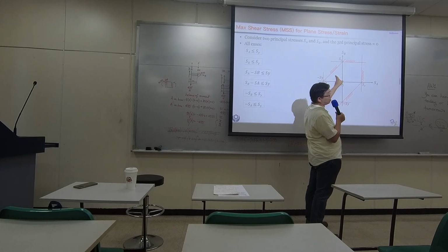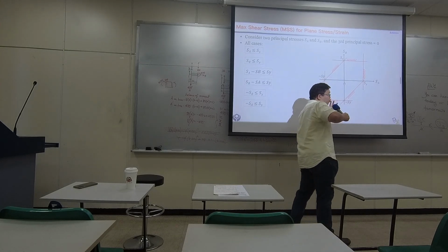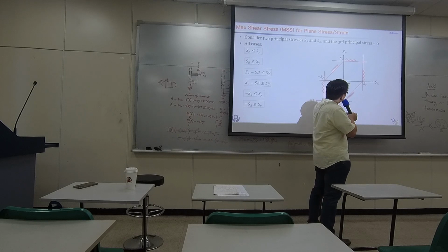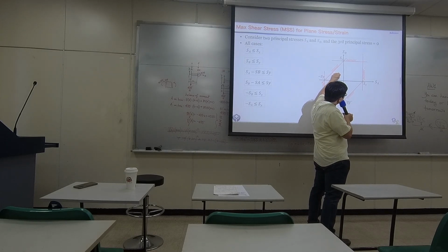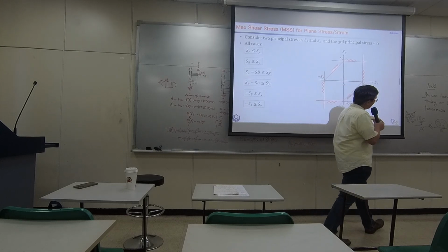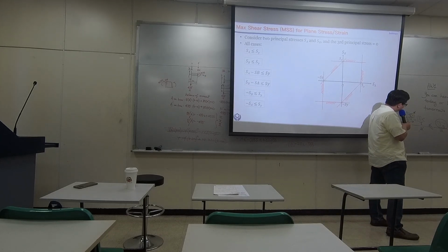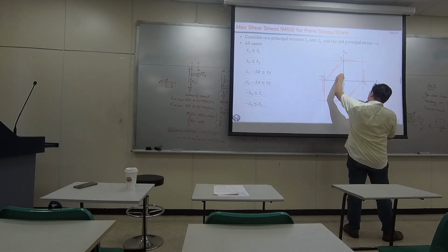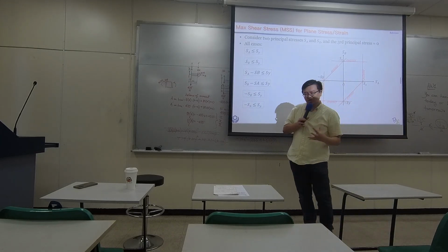And this similarly. So if you make your load smaller, then your design point goes closer toward the origin. If you enlarge your diameter, similarly the stress goes down, then your design point goes closer to the origin.